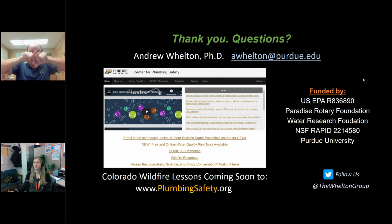Now, that's the pipe itself. If we have fire hydrants that are metal, and we have metal barrels that go down, you can conduct heat. And so there are no really insulated, fireproof fire hydrants that protect the water mains from that. So there could be conditions where you could have localized damage to the water mains because the fire hydrants got so hot and conducted that heat downwards.